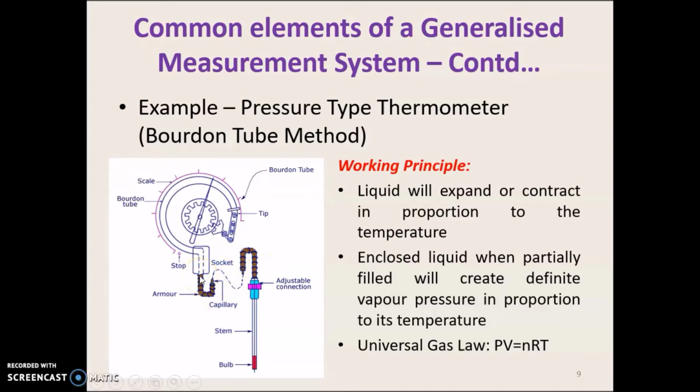After the data gets transmitted, is the converted signal enough for reading? No, it needs some magnification, that is, variable manipulation is required. That is the reason we use this Bourdon tube, which is blue in color. Here, based on the pressure, this Bourdon tube is going to get magnified or expanded. So this is where we call it the variable manipulation element.